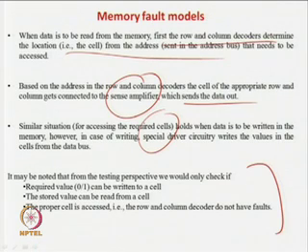So what do you require to test RAM memory? There is no other logical function, except that you just read some data and write some data, that is it. You do not need any kind of ANDing or ORing. So what are the 3 tests you want to do? First, a value of 0 or 1 is written in a cell, and you should verify that each cell can be written to be 0 and 1.